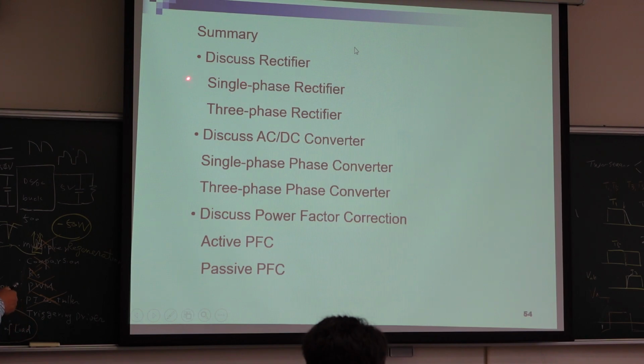So what can you do? You have to use your own brain to simplify it, to design a simple PFC. And we discussed AC-DC converters. For AC to DC, in general, we need two stages. The first stage deals with the PFC. The second stage deals with the load voltage regulation. So we need two stages, and we need a lot of control, a lot of feedback. Then our price becomes very high. So this is the problem.